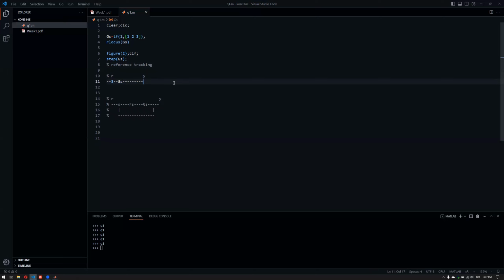Well, you are actually relying too much on the transfer function model given in line 3. So you are relying on the mathematical model, and if for some reason something happens, or if you have an erroneous model here, which means that it could be 2.9, for example, and not exactly equal to 3, then your strategy will actually start to fail. But of course, in this case, it's not that big of a deal because it's 2.9 and then 3. That ratio will cancel each other out, and it will be roughly around 1.